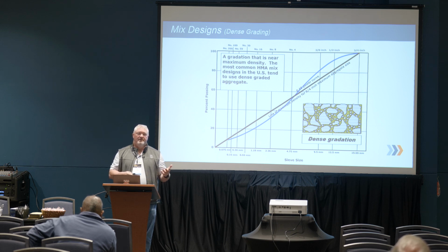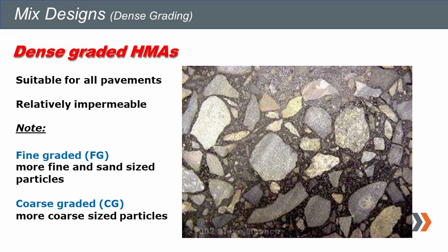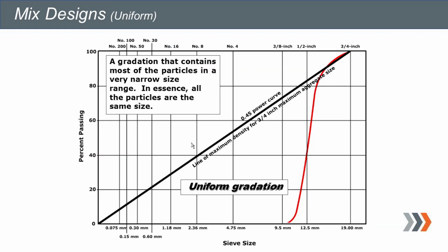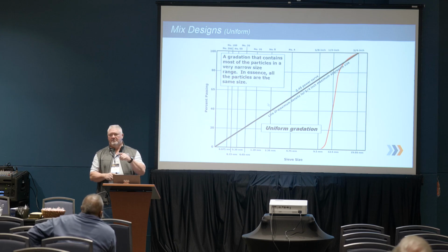Could be coarse, could be fine, depending on what is available for materials at the time. We have single size material with a very low AC content. Did a project up in Rockford, Illinois at the Rockford Airport. We did 2 4-inch lifts, 3/4 inch rock, 2.2% AC.